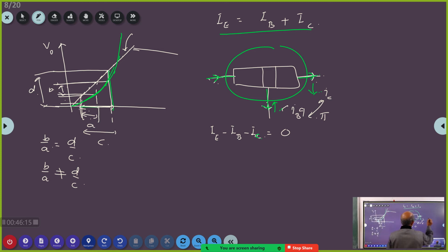So what I am trying to tell you here is, now I told voltage amplification, AV. AV is what? Delta VO AC divided by delta VS. Agreed? Voltage amplification. Similarly, I will write something as current amplification. What is current amplification? Delta IC by delta IB. Agreed?